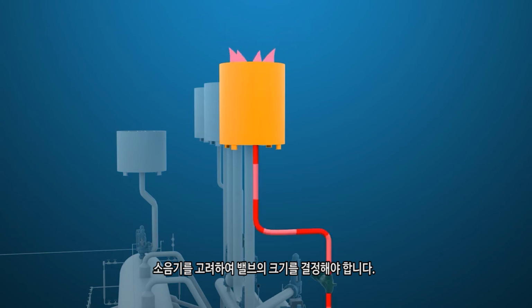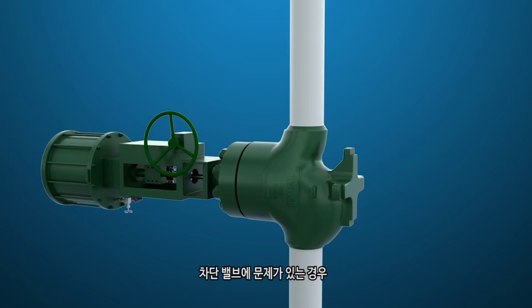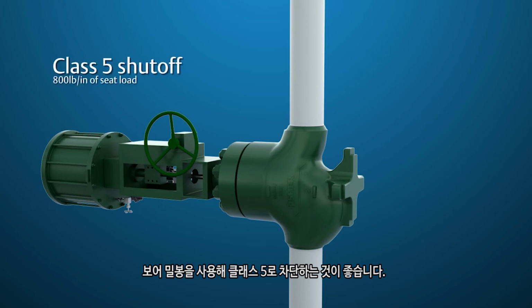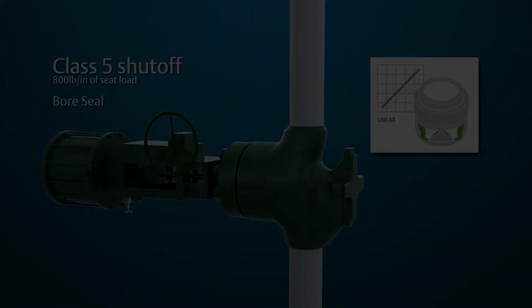While there is generally an isolation valve upstream of the control valve, it is important for the sky vent valves to shut off tightly in the event there are issues with the isolation valve. With the high steam temperatures, Class 5 shutoff using 800 pounds per inch of seat load and a bore seal is recommended. Additionally, since the differential pressure is relatively constant, a linear trim characteristic should be used.